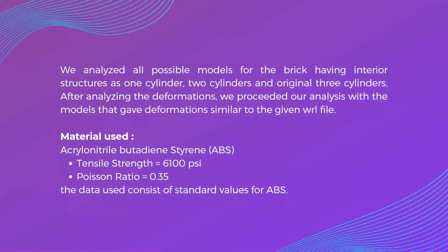For taking the tube diameter, we used the space between the studs at the top, and we simulated with different tube radii so as to obtain stress results closer to the given value. We also tried other methods besides using tubes, but the results were not similar to the final value,